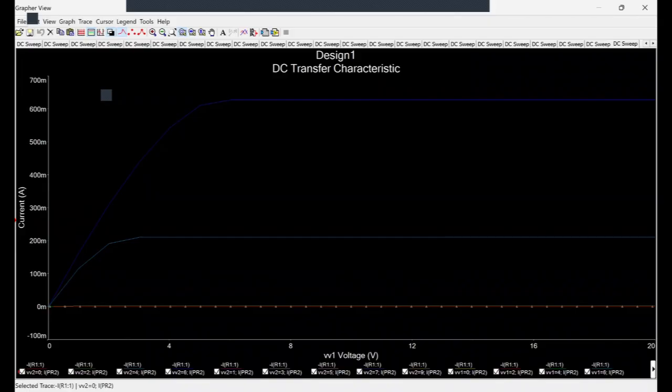Okay, and as the voltage between the drain and source increases, the current will increase until it's saturated and is constant. Same goes when we apply 6 volt between the gate and source, which, as we can see, would increase until it gets saturated as the voltage between drain and source increases. And you can clearly see this is the border that we earlier showed on a board. So we have a triode mode and a saturation mode.